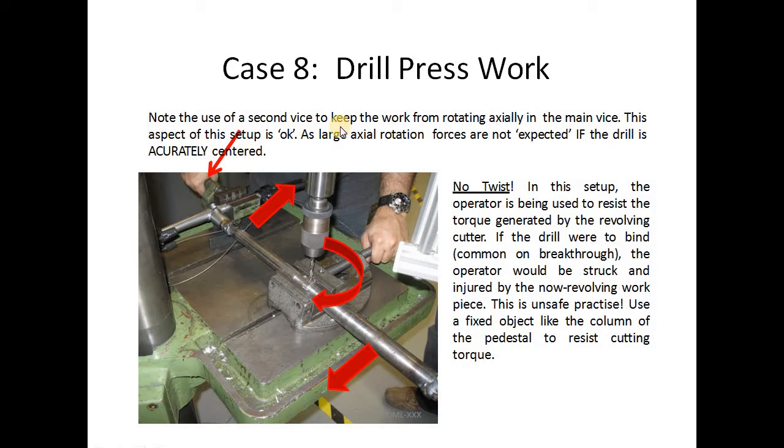This setup is okay, as large axial rotation force is not expected if the drill is accurately centered. In this setup, the operator is being used to resist the torque generated by the revolving cutter. This revolving cutter generates the torque.